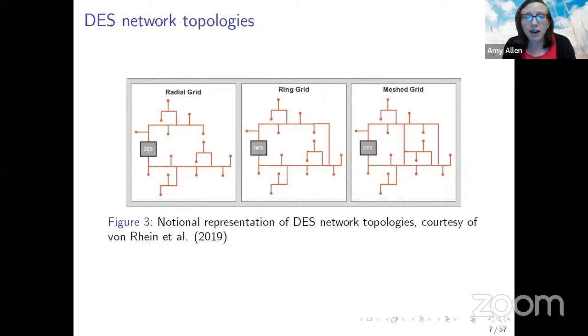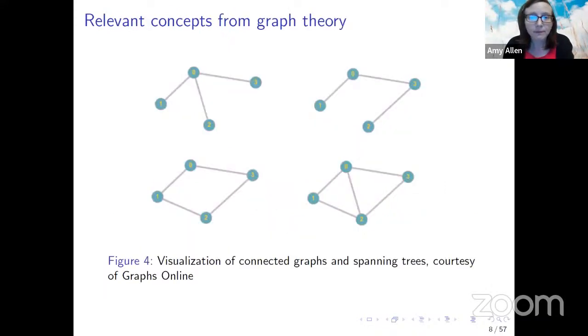The consideration of this type of network configuration is motivated because each connected load can also be viewed as a source of heating or heat rejection to other loads in the network. And thus, with this wider search space of network configurations relevant in the context of 5G DHC systems, network topology optimization becomes increasingly important.